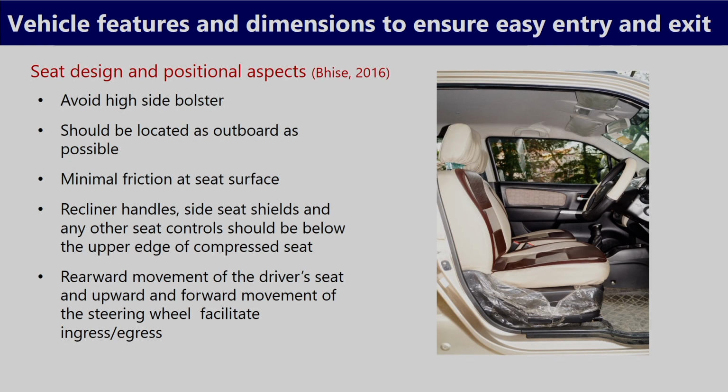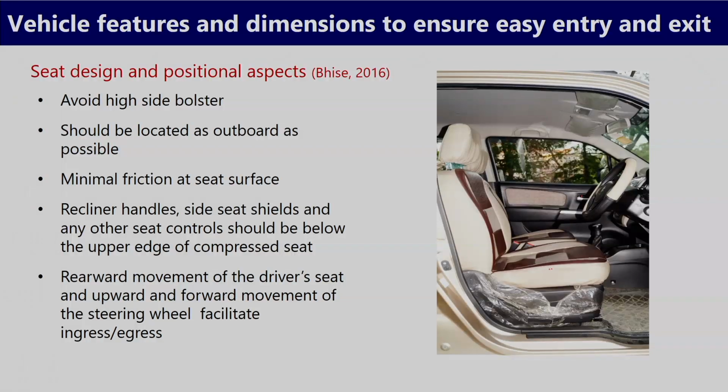Now, seat design and positional aspects. Where the seat should be positioned and what design aspects of the seat facilitate comfortable and easy entry and exit. First, we have to avoid the high side bolster. If the side bolsters are high, it will create problems in the entry-exit process.